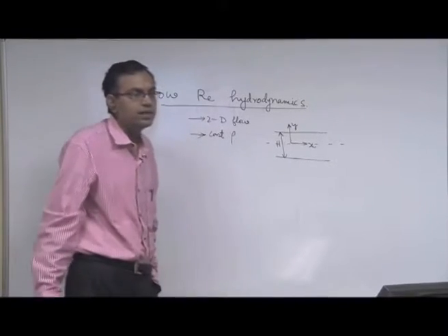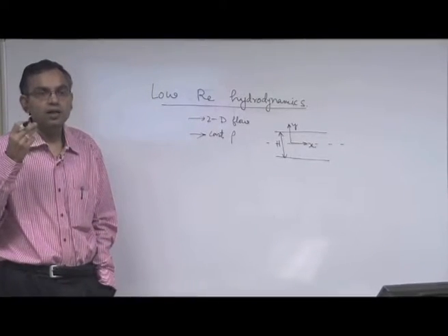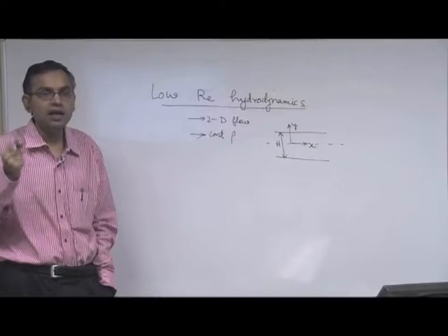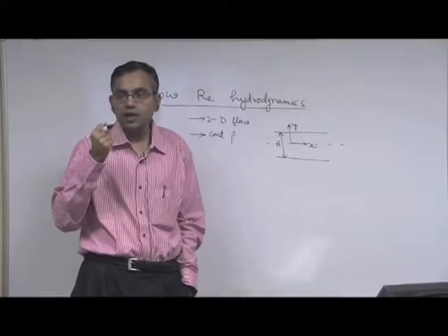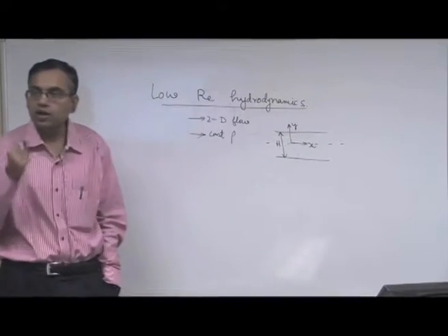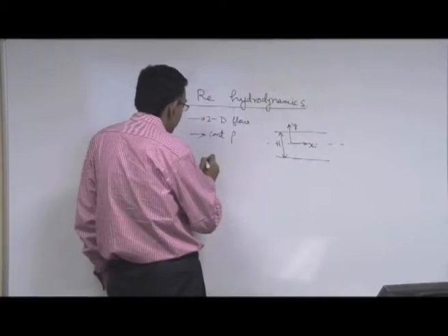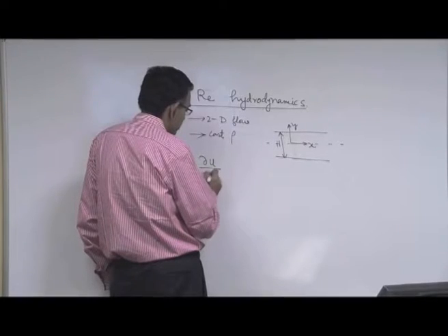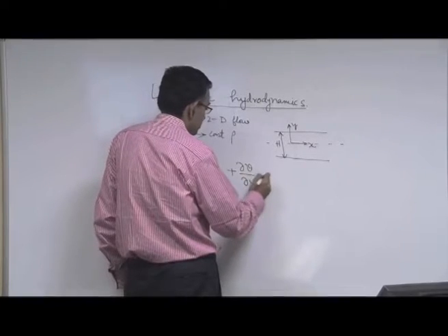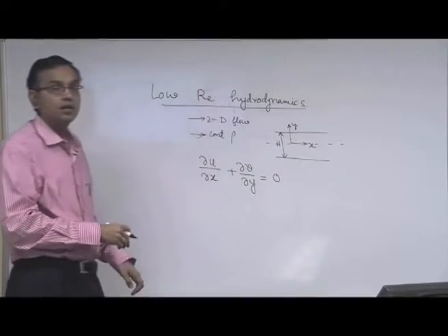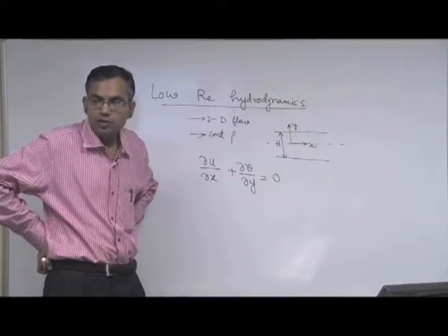So what we will do is basically we will first figure out what are the scales of length, velocity, time, etc., length scales, velocity scales, time scales in describing the very basic hydrodynamic problem, through the continuity and the Navier-Stokes equation. So we start with the continuity equation. So you have del u del x plus del v del y equal to 0, right.